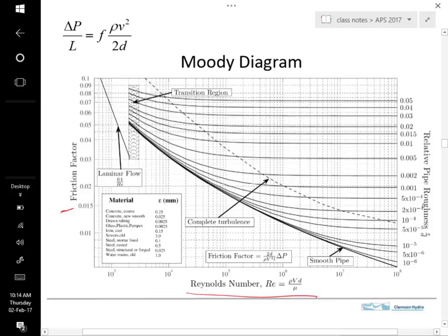Okay, so you have flow down a conduit, and the surface of the conduit is going to play a big role in the friction. So what was done is Moody, I guess, was the guy who did this series of experiments, and worked out what this f term is at various different Reynolds numbers for various different types of pipes.